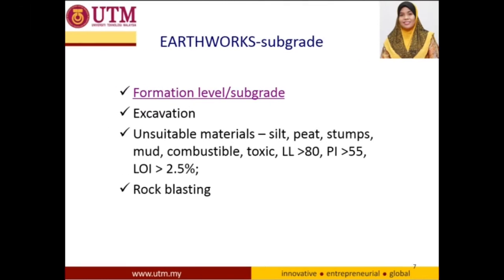Next, after the clearing work is done, the earthwork will take place for preparing the formation level of the subgrade of the roadway. The excavation involves the process of removing earth from the cut area and transporting it to the fill area. The unsuitable materials such as silt, peat and stumps are disposed of, and it may be necessary to replace the soil with satisfactory material.